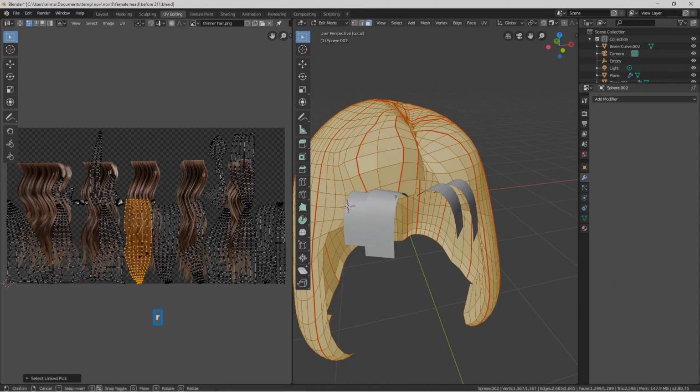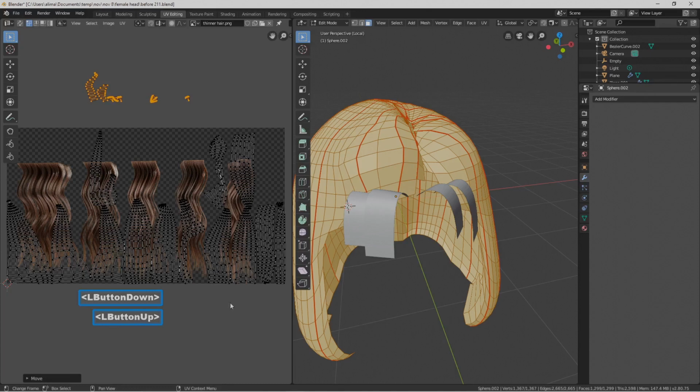L, R180, enter. Select here, L, R to rotate on 180 degrees, press enter. L, R to rotate on 180 degrees, press enter. These ones look right. I'll select here, press L. These small pieces here, we'll press G to move them up as well as away.